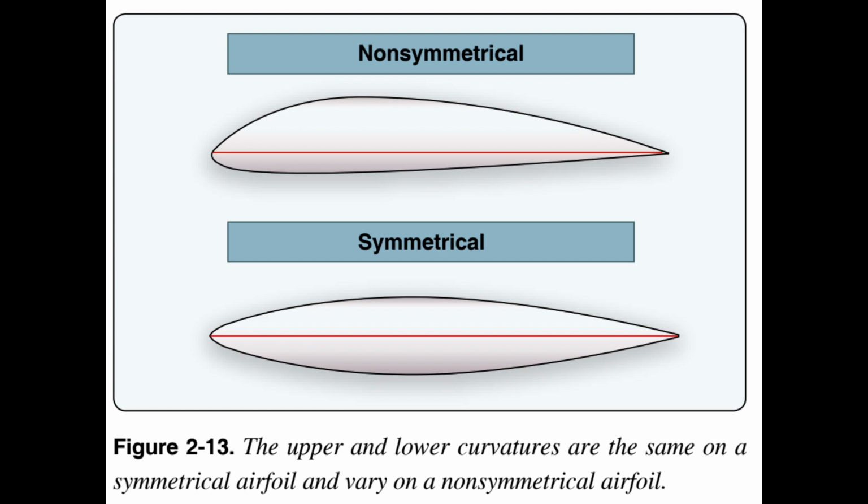The advantages are more lift production at a given AOA than a symmetrical design, an improved lift-to-drag ratio, and better stall characteristics. The disadvantages are center of pressure travel of up to 20% of the chord line, creating undesirable torque on the airfoil structure, and greater production costs.